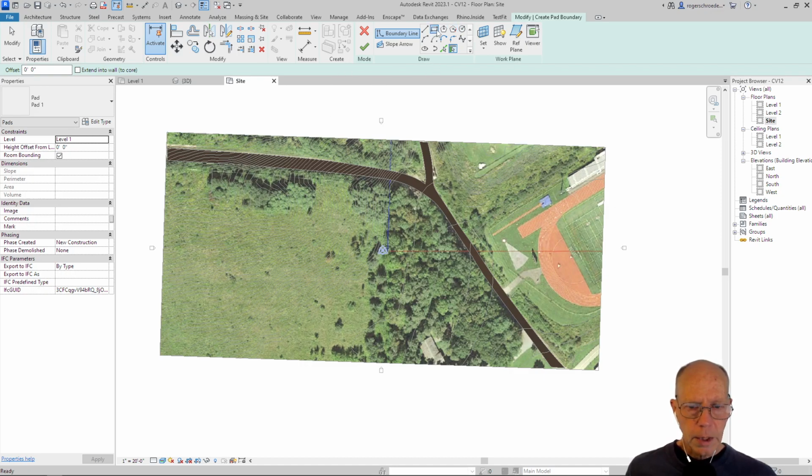I'm going to use the rectangle mode, and I'm going to put the building pad kind of up on the hill in a clearing here out of this treed area, but you'll notice the contour lines are very close together, so that indicates that it's really heavily sloped. So we may want to just not be in the thick of all the slope. Maybe I'll come down here a little bit, and I'm going to make this about 120 by 120 feet. Not critical, we're going to make a lot of adjustments to that.